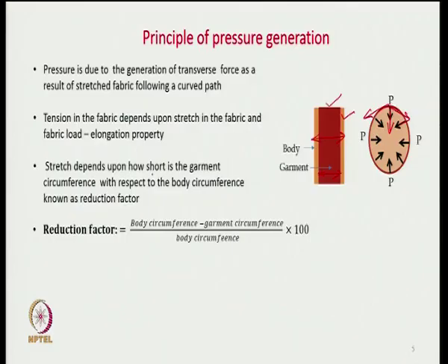So, stretch depends upon how short the garment circumference is with respect to the body circumference, and we define it by a factor called the reduction factor. The reduction factor is the circumference of the body minus the garment circumference, where the garment circumference is less than the body circumference, divided by the body circumference and expressed as a percentage. That will be the reduction factor in percentage terms.